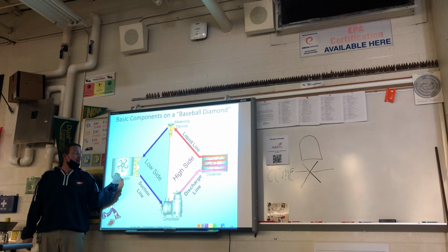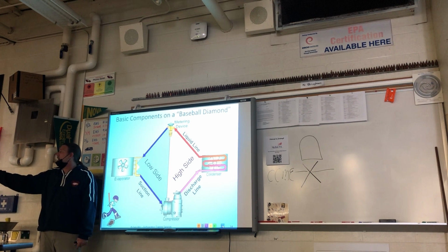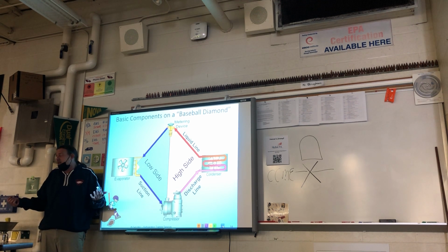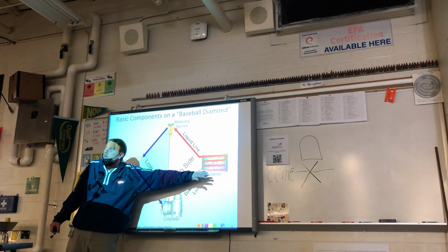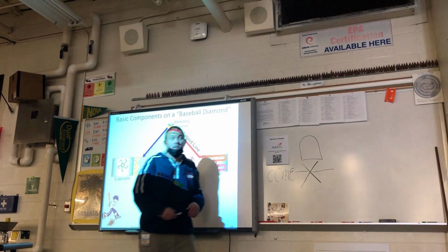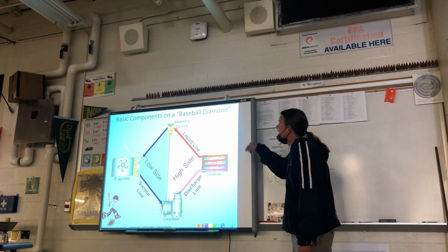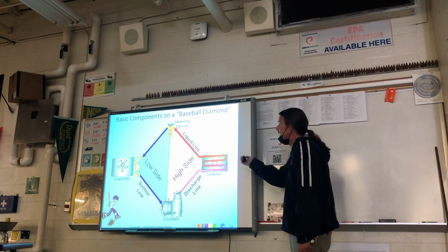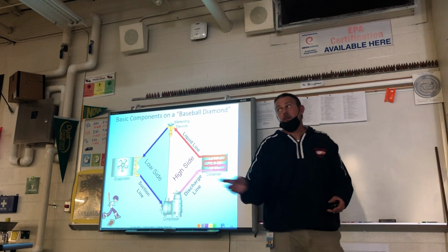And then on our evaporators, pretty much for a lot of these, they're what they call direct expansion. But in our chiller, we got one that's called a flooded. It's a little different. All right? So there's a couple different types of condensers as well. Water-cooled, air-cooled, and then evaporative cooled, which we don't really get into too much on our entry levels. But if you can get this down, this is a good stopping point for today. Because again, I'm going to break these components down even deeper with you, and we'll take it from there another day.